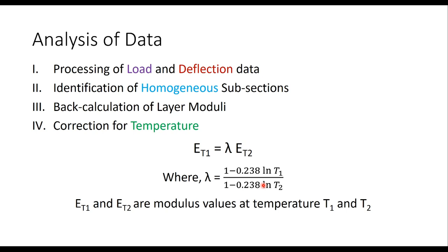Now, once you get the data, we need to process the load and deflection data. So, back calculation of layer moduli. Using this deflection profile, we make use of software to calculate the elastic modulus of different layers. Now, the elastic modulus of different layers is corrected for temperature using this equation.